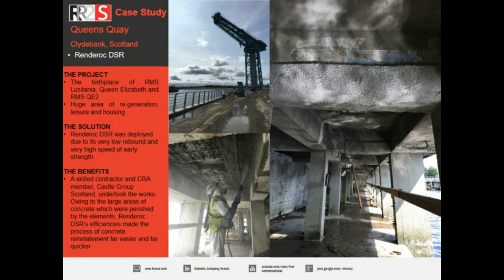But the other beauty of having a material that is very fast curing is that if there are areas overhead or vertical areas that you're having to layer up because there's so much material needed to be reinstated, you can actually get your layers put on a lot quicker, because the first layer will essentially be tough enough after 15 minutes to then get a subsequent layer put on. So yeah, there's two factors really that come into the success in that type of project.